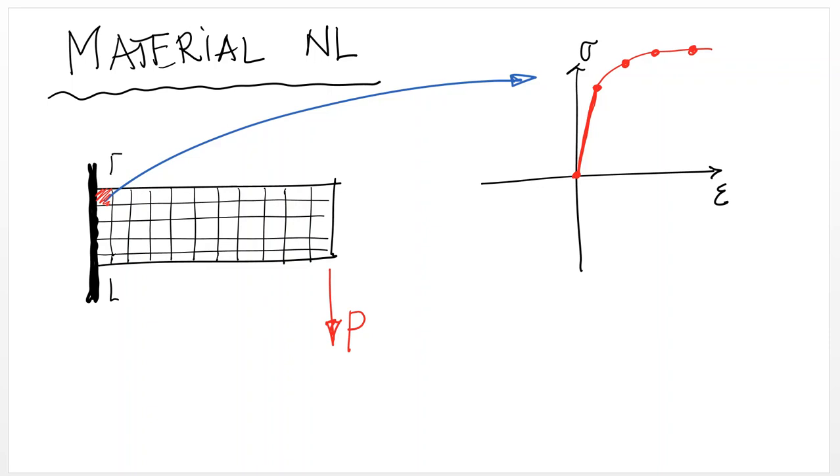If you integrate those stresses in a given cross-section, you will integrate to a moment. That moment now will have a nonlinear effect because it's integrating stresses and strains that are nonlinear. And if you integrate that moment throughout the length, then you will end up with a nonlinear force displacement relationship as a byproduct. So this is a case where force and displacement will exhibit a nonlinear relationship due to not necessarily large displacements, but the constitutive material going beyond the linear elastic range.